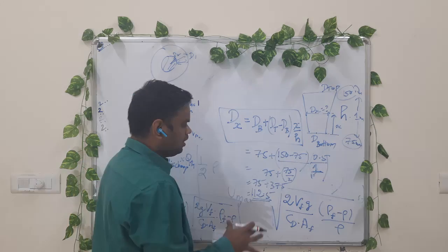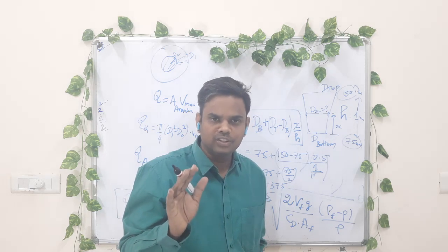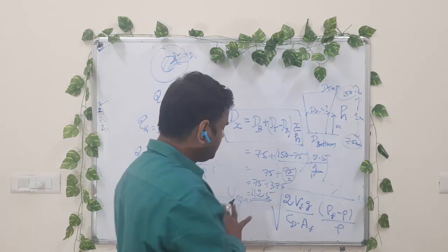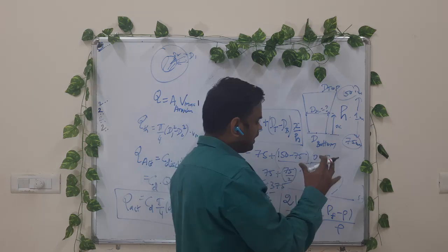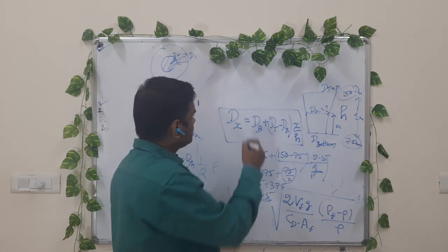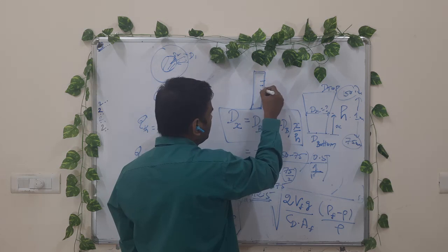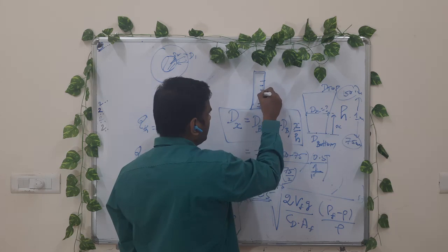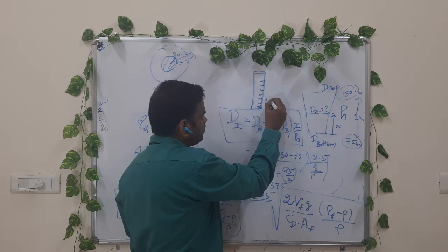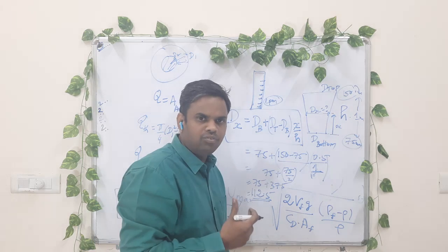This is only for understanding. The advantage with this rotameter is that we don't need to do any calculation when we are using this type of flow measuring device. We have a calibrated scale. Using these relations or equations, at a particular height we know the diameter, and at that diameter, whatever the velocity is, we fix accordingly. The calibrations are based on these equations. So we get a ready-made value for the volumetric flow rate whenever we use this type of rotameter.